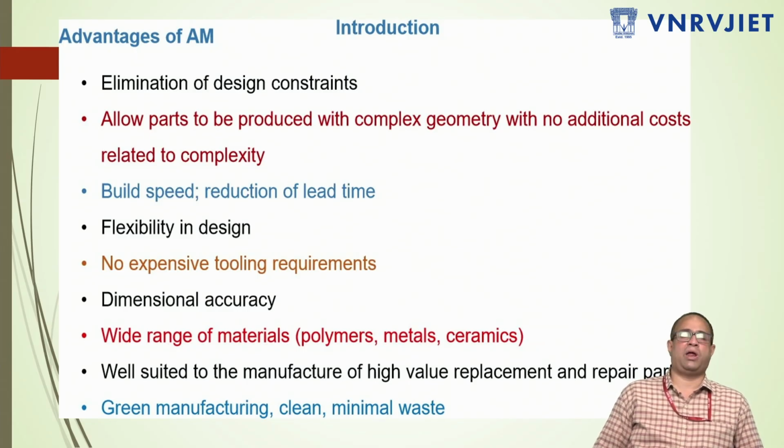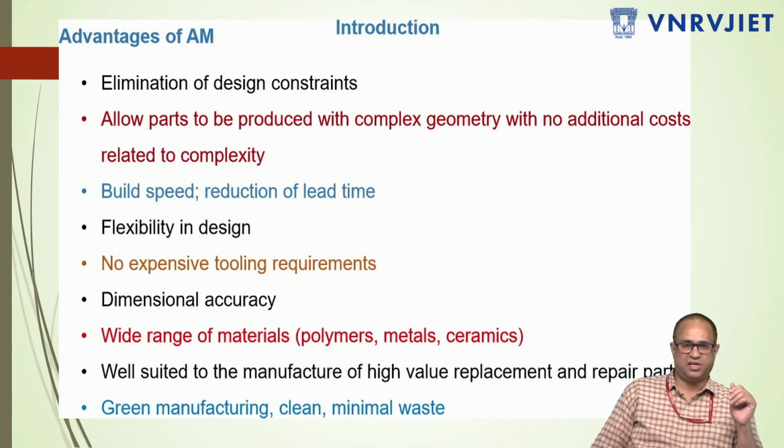If you go for subtractive manufacturing, it is quite difficult to do this sort of replication, because it is equipped with costly tooling, and this cost can be completely reduced by using additive manufacturing techniques, whereas we can do repeated models. When you compare to subtractive manufacturing, no expensive tooling is required, dimensional accuracy is maintained, and there is minimal waste.